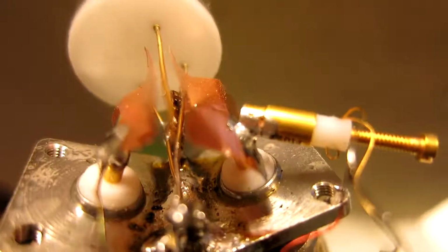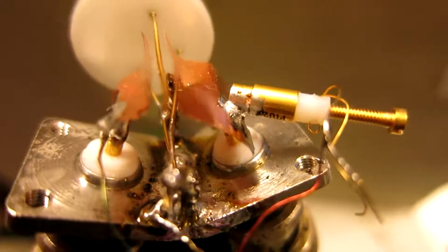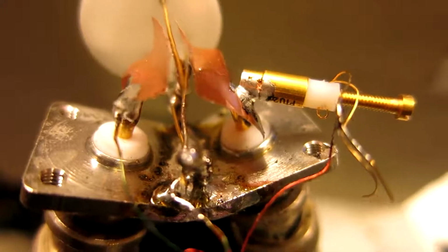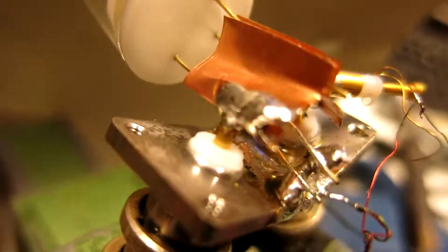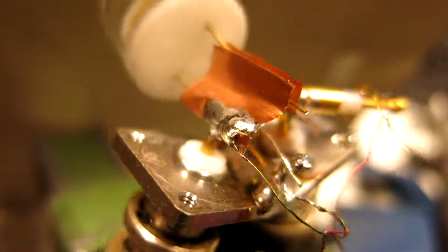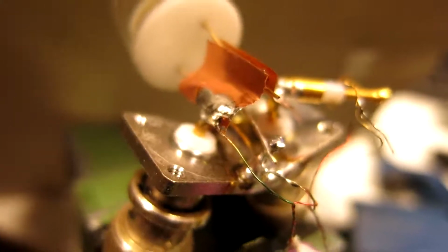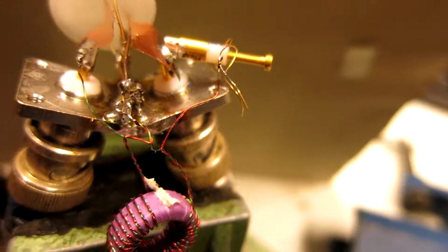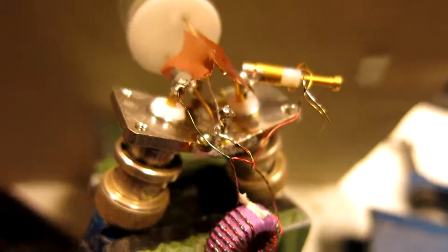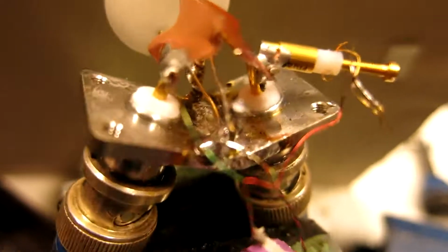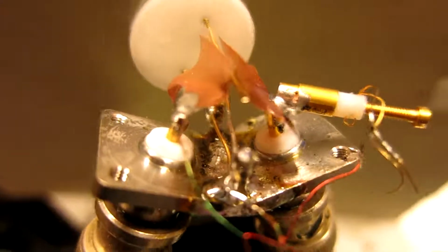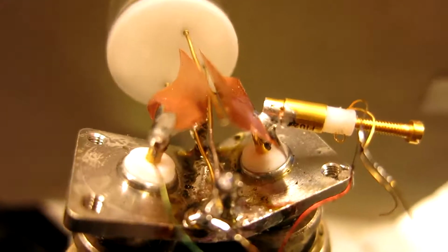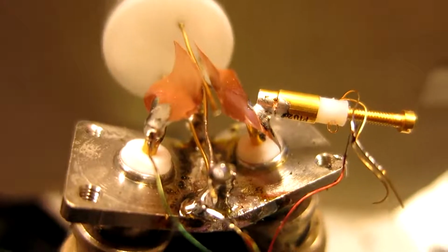So I have connected the crystal to two very small capacitors with air dielectric. It's these two small pieces of copper, one from each side, and they couple to the wire from the crystal. And then I have a transformer and another capacitor to balance the capacitance between the two copper sheets. So I think what I can see now is the performance of the crystal itself with no capacitive load, almost.